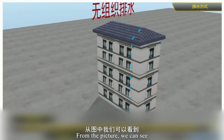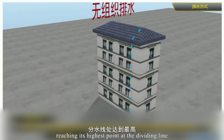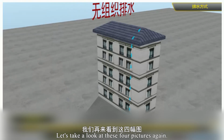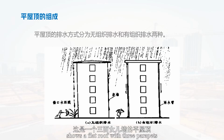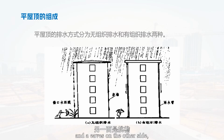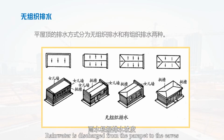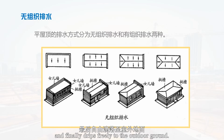From the picture, we can see this is a slope where rainwater flows through the roof, reaching its highest point at the dividing line and flowing down from high to low. Let's take a look at these four pictures again. The first picture shows a flat roof with three parapets and the eaves on the other side, with only one drainage slope. Rainwater is discharged from the parapet to the eaves, according to the drainage slope, and finally drips freely to the outdoor ground.